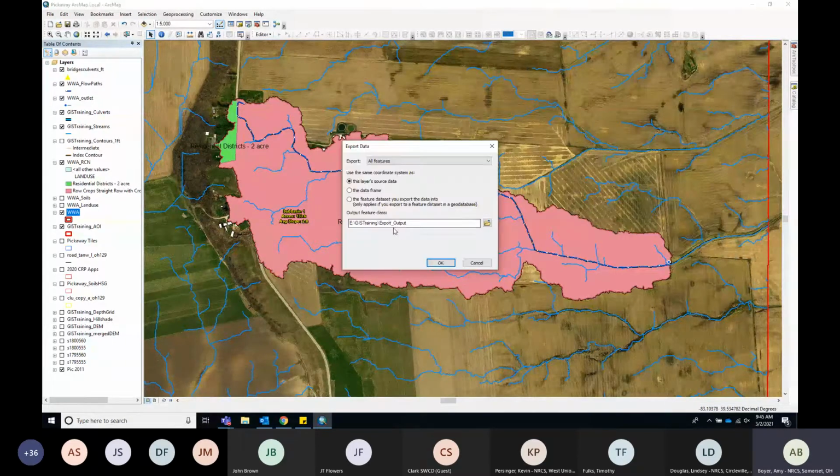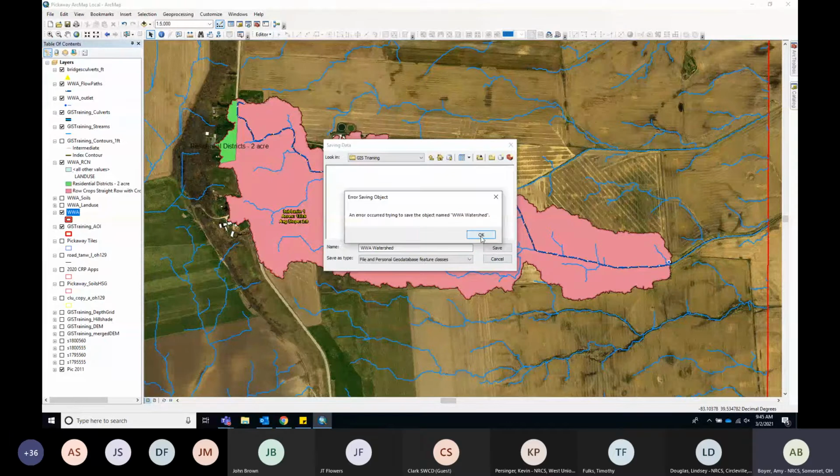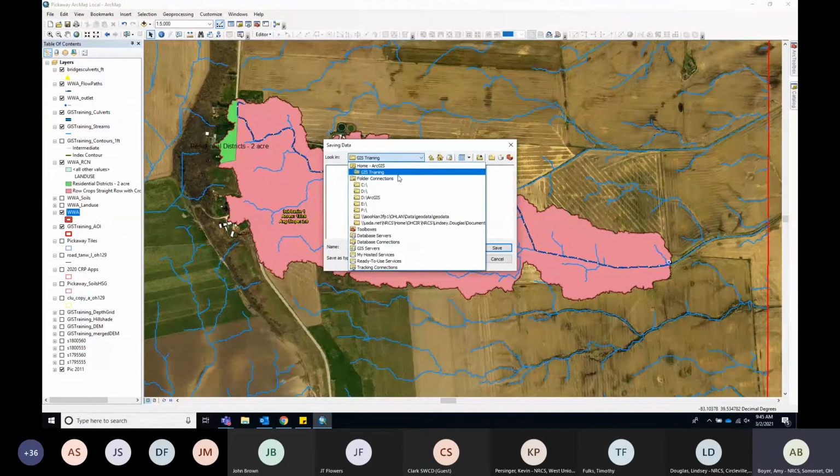And we can do double duty with some of those files that it's going to create. First of all, we can import that into our web soil survey to be able to get a breakdown of those soils. We can also take that exact same shape file and put it into AutoCAD, if you're using AutoCAD, and that's going to give you your watershed map in your AutoCAD, which is required on an engineering plan.